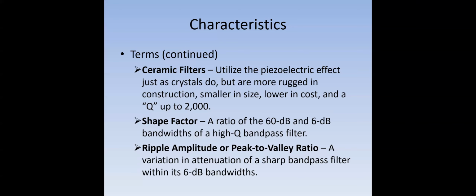They're better when it comes to rigidity because some of these filters get placed on aircraft, jets, and stuff like that. And when you talk about pulling a lot of G's on an aircraft, you don't want these components to flex or bend or anything like that. You want them to be stable. ICs are a little bit different, and we used the 741 op amps previously in your last class to create filters, but we will be using the passive filters on this.